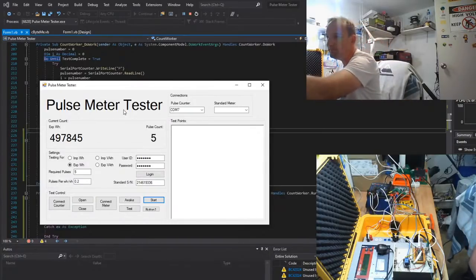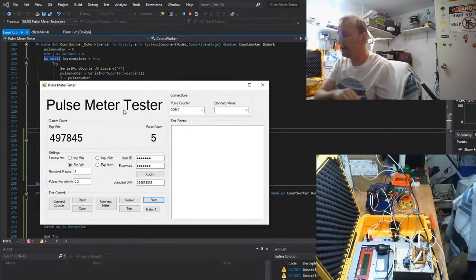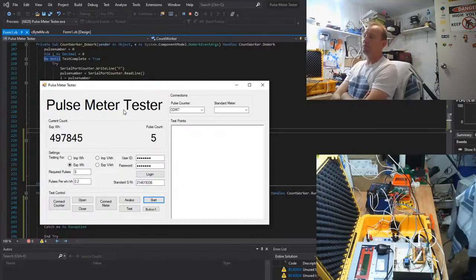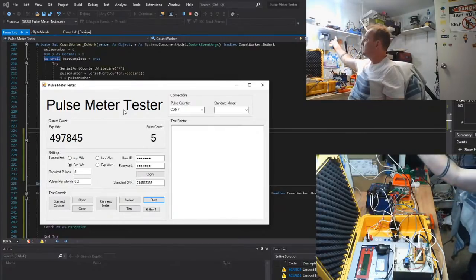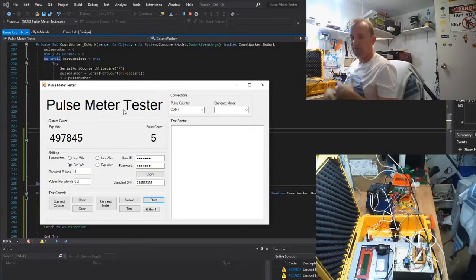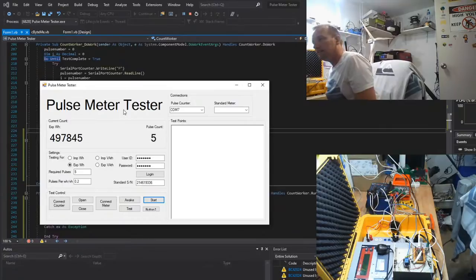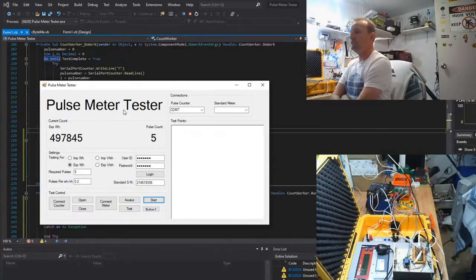So that's actually the amount of pulses I've got from this blue one for 5. That would be 4.97845 watt hours, against the 5 watt hours that the Mark 10 thought. So it's a little bit in front, which is annoying because you'd really want a meter to be low. That way the customer gets that little bit for free, kind of. But anyway, guess not in this world.